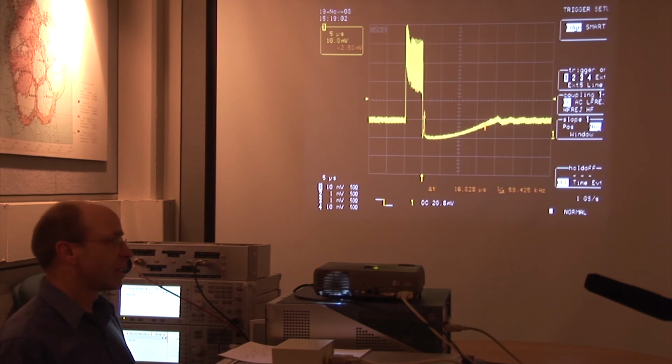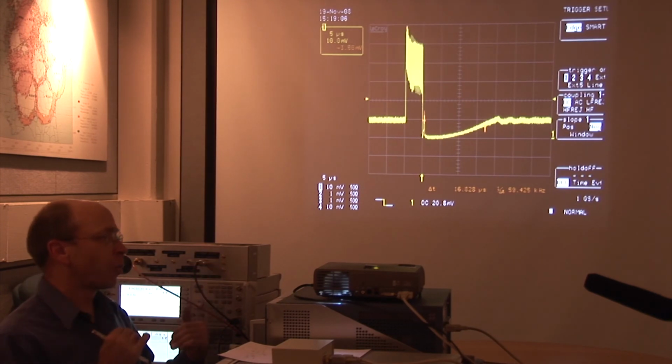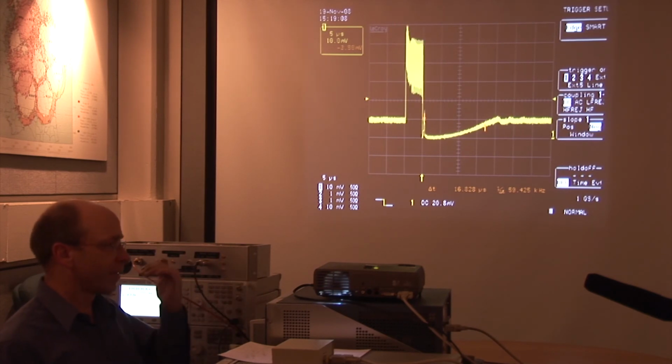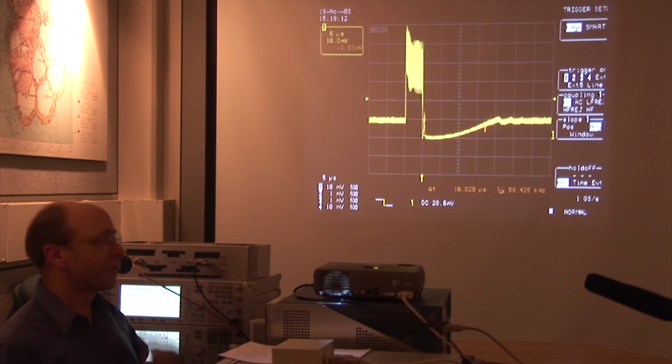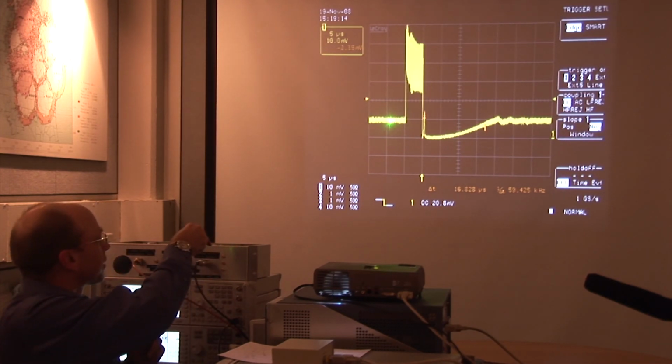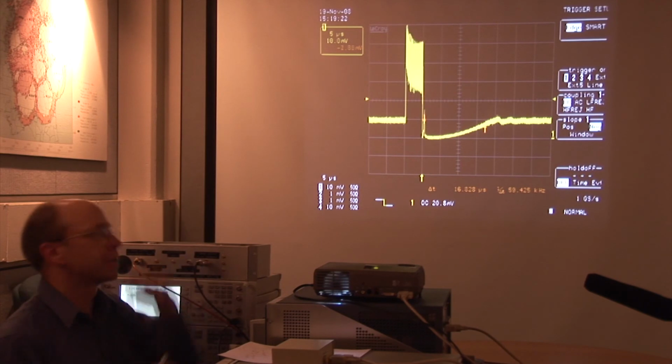Then I would connect the antenna and see if that receiver's gain characteristic had dropped when I connected the antenna. Because if it drops when I connect the antenna, something's coming in from the outside world that's making it drop. And if it's a continuous source, we won't get to see this transition occur. We would see it depressed down there all the time, but we would have seen it come back up to that level when the receiver's antenna was disconnected.